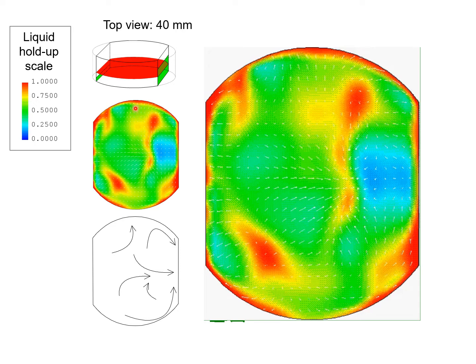Difficult to say conclusively, but there appear to be regions which are almost circulatory in this direction here, but overall the flow is from the inlet to the outlet, but the up and down motion is restricted to 4 different regions, indicating there are 4 well-mixed pools, but you can't tell conclusively from this view.